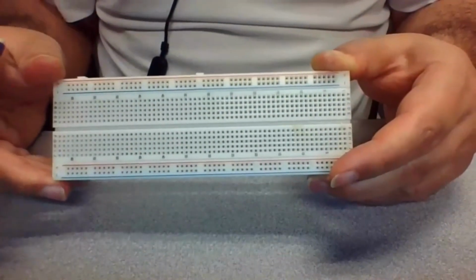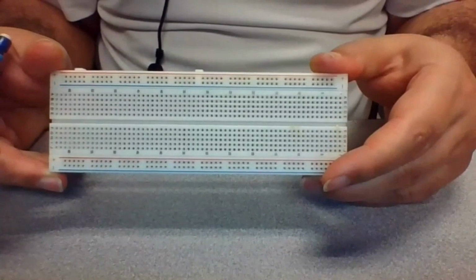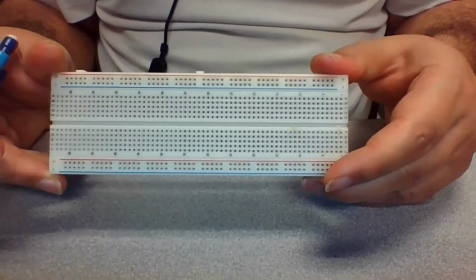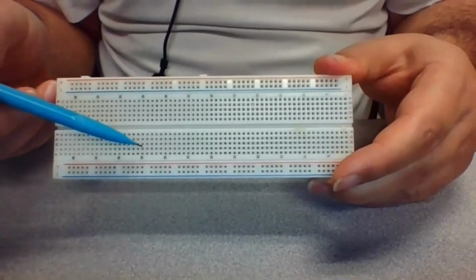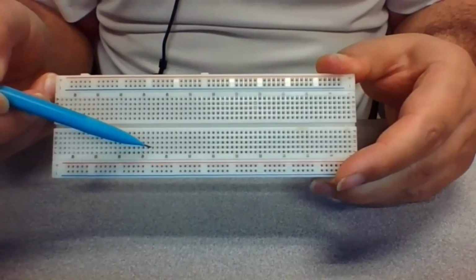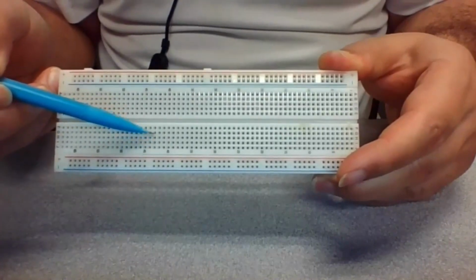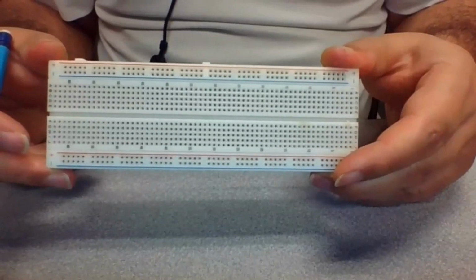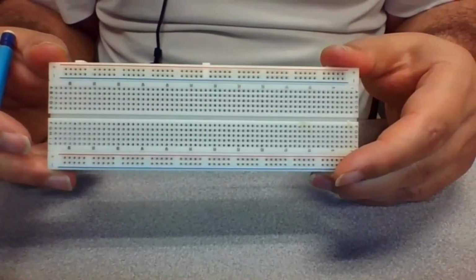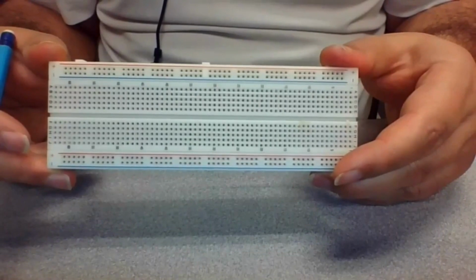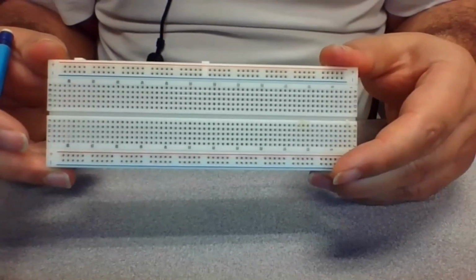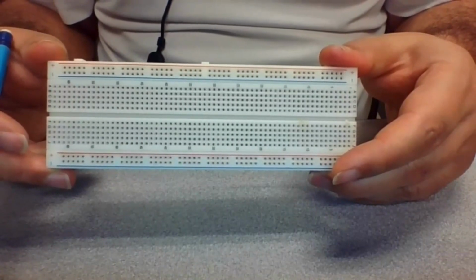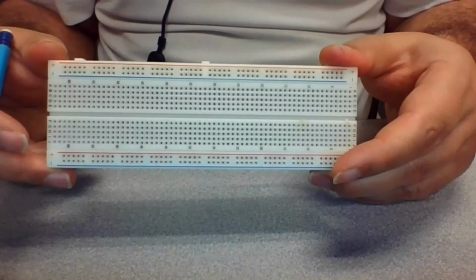So that means whenever you want to implement or prototype your diagrams, you don't need soldering and you don't need anything. If you want to connect 2 points, you just need to put those 2 wires inside one row. So that means you connect them. Okay. For our case, we are going to implement the LED flasher diagram in this breadboard, make sure the circuit and diagram is right, then we will move to design that in EasyEDA.